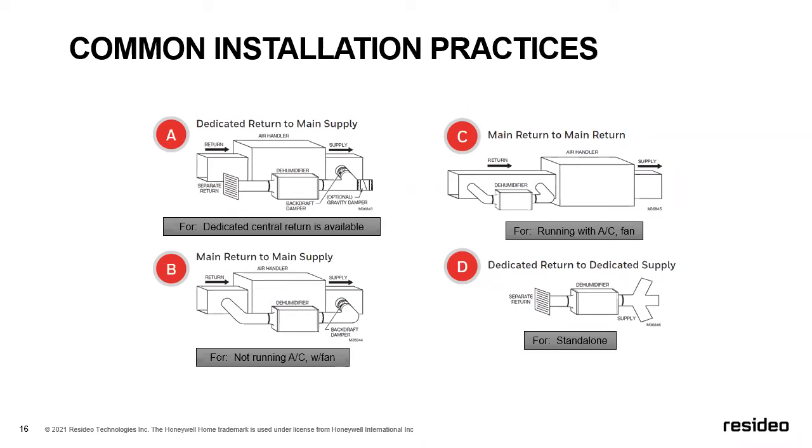D, so this is when we start talking about best, better, good. In Florida, one of the things that we realize is locking out that dehumidifier and not having it running. Most of our applications would really, really benefit from the dehumidifier being somewhat of an isolated appliance that it can take off and run as needed. So in D, unfortunately, that may require some conversations with our homeowners that are going to allow us to maybe add a return, and we don't necessarily need to add multiple discharges from our dehumidifier. Maybe it's one in a high foyer area or somewhere in the home that we could discharge some warmer air that wouldn't affect the homeowner.